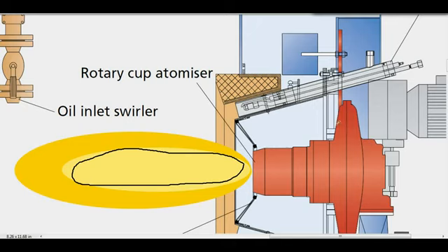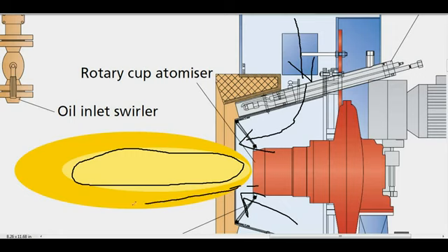And the secondary air, which is coming from the top through the forced draft fan, enters here, comes over here, and then extends the flame a little bit more and makes a complete combustion. Thus the secondary air or the extra air is required for complete combustion of the fuel particles.